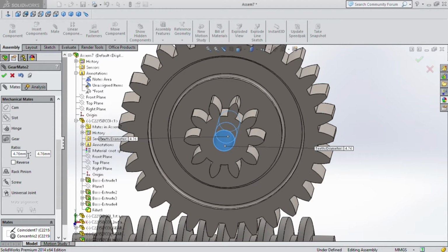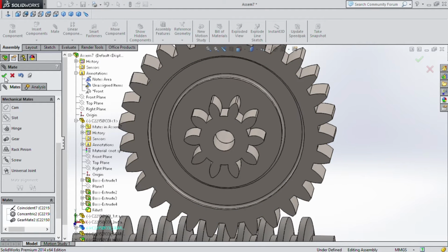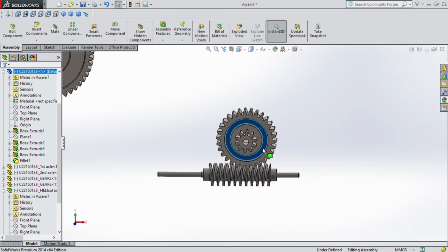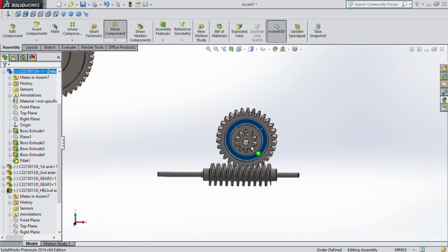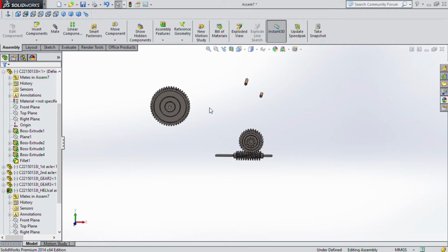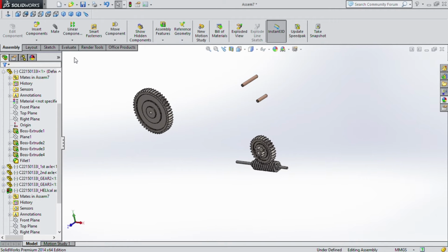Okay, here it should be 1:1, so 476 and 476 is just the same as 1:1, so we can just maintain. And then what this does is this gear and this gear rotate the same, which is what we want, and we can be happy now. Okay, done. And what we want to do next is go to Mate.